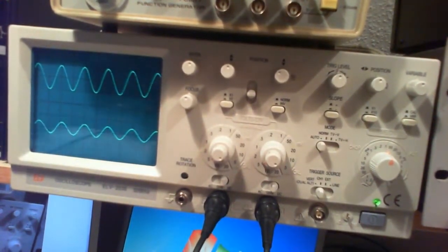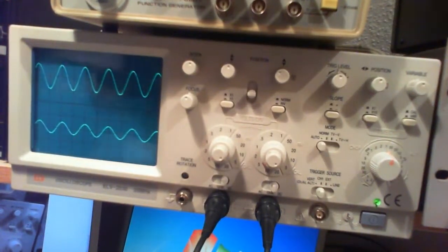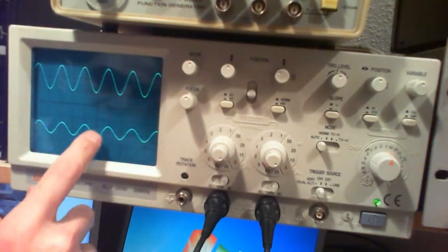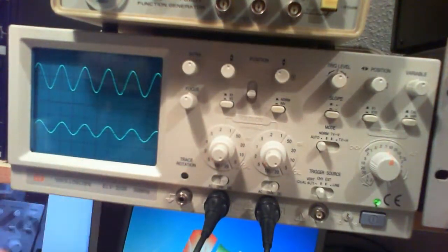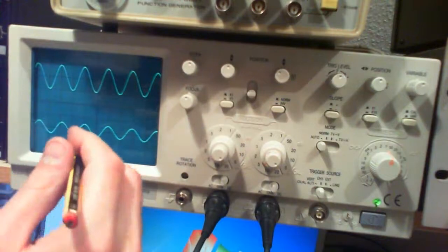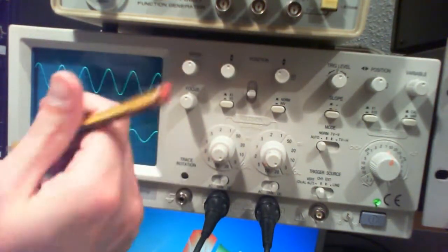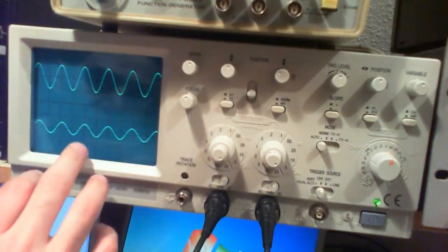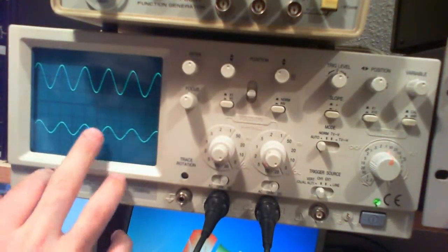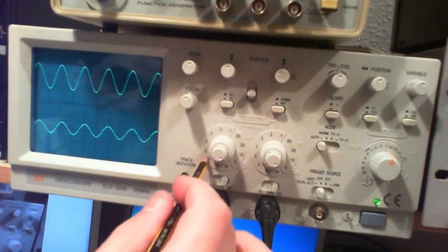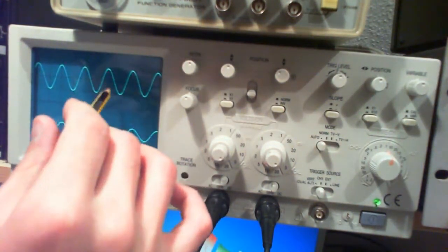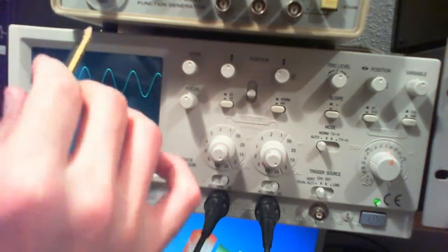coming from your input, and of course your output is the same thing as your input, but going through basically the resistor and the capacitor and so on and so forth. So the same offset that you have on your input, you have on your output as well, but it might actually be a little bit different. And you see that the offset that we had on the input was actually 10 volts DC.